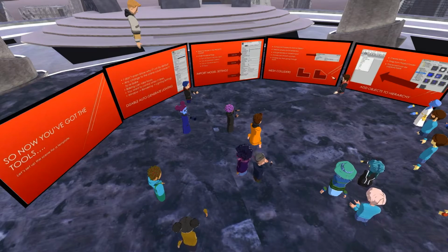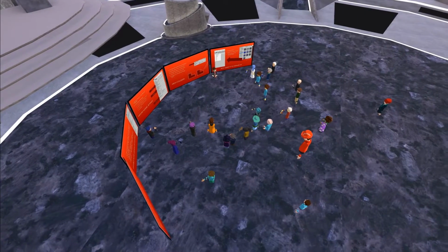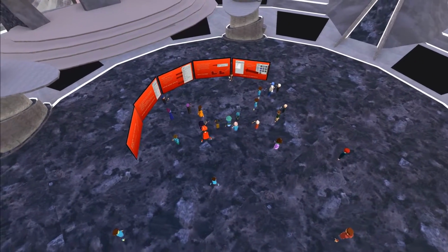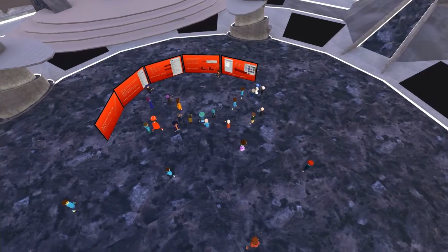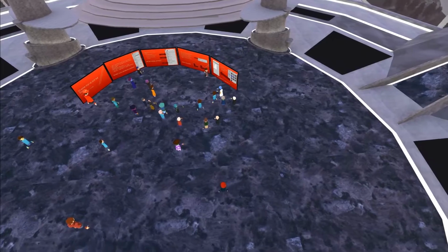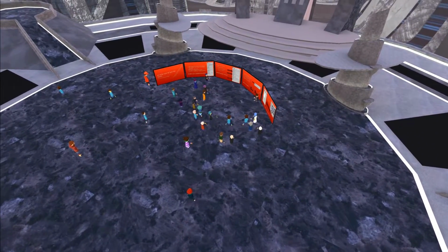Now, what difference does this make in Altspace? Most of the time, I just use the regular mesh collider because it's simple enough, right? And it'll follow nice slopes, and I'll be able to go up gradients and over humps and down through dips and stuff. It'll be nice and smooth. But stairs become bouncy. So if I build a set of stairs and I bring that stair object in as one model and I give it a mesh collider, I'll be able to walk up it, but there'll be this annoying jitter every time I go up each step.